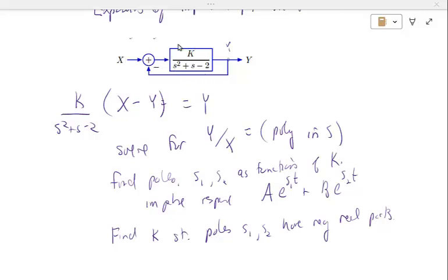So this is representing some system that could be represented using the conventional circuit components, but instead of doing the algebra with the integral block, we're doing it with s. So the same rules apply, and this x and this y should be considered as the Laplace transforms, and not as the signals themselves.